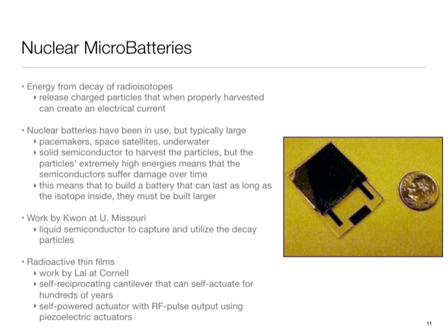How much size? Like, in the sense that if you are a Samsung trying to put a large battery for your Note 7 to burn, a lot of thin film batteries will not be a good choice. Well, I'm kidding, but point is that if you have a lot of volume, then you don't gain any advantage from thin film. Okay, so the thin film shines when you are putting a tiny amount of battery in a space limited kind of a setting. And thin film is obviously, as I said, cost. So that would be kind of nice for something like an oscillator or a clock. Implants, wearables, these kind of things.